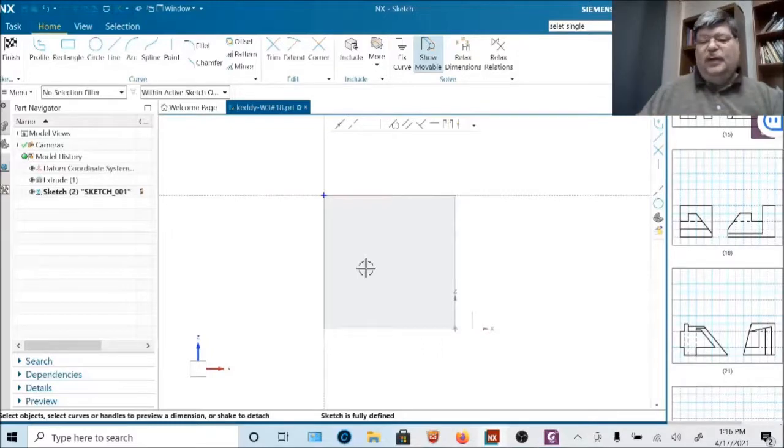Okay, so you'll find out that sketching and extruding works, but if you can model it or change the model with another command that changes the model itself without drawing another sketch, you want to do it that way. We'll get into that. You'll pick it up on it fast because sketching, you need to sketch it, you need to constrain it to geometric and dimensional constraints, and then you need to come out and extrude it. If you could just work with the model itself, that would be faster, wouldn't it? Okay, so let's draw this thing.